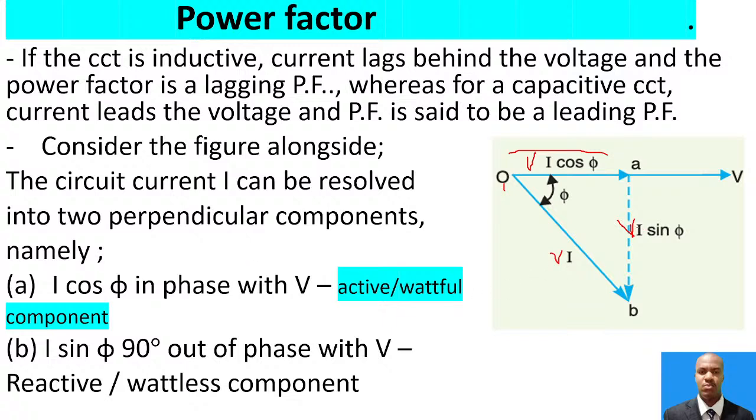Then again, on this side we have the wattless component or the reactive component, and this is the power that simply loiters within the circuit. It flows back and forth in the circuit. It has no use, it is useless power. In other words, it is the wattless component, so it has no use in a circuit.